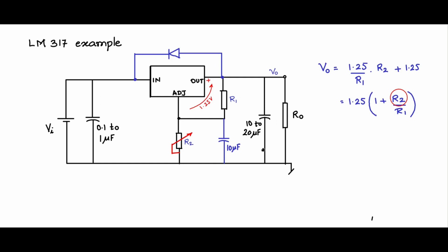In order to speed up, we can put a diode like this, in which way this capacitor can directly sink into the output or sink into the input. So these are some of the protection features you add, and this will make it a workable circuit.